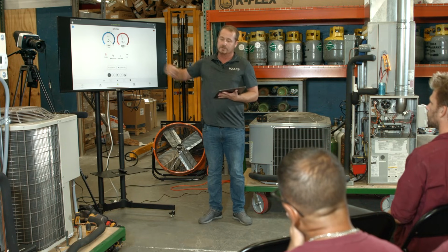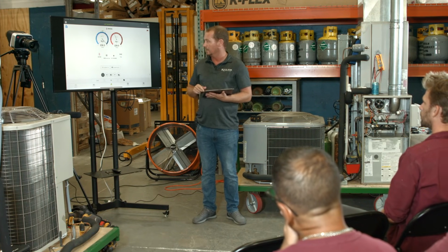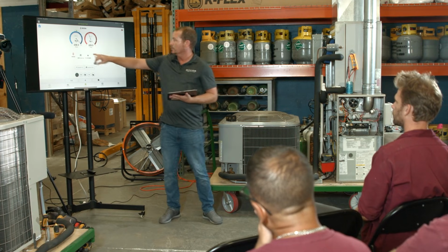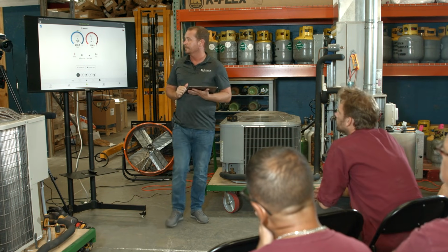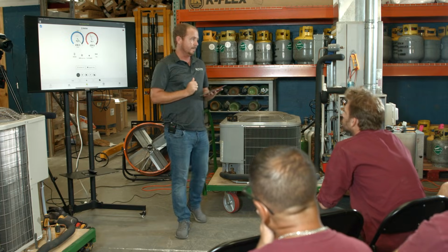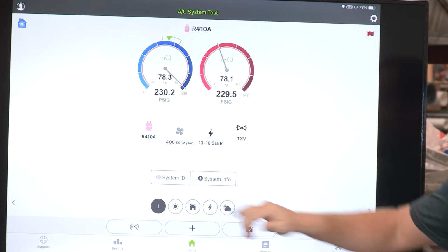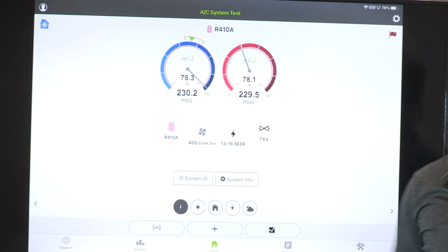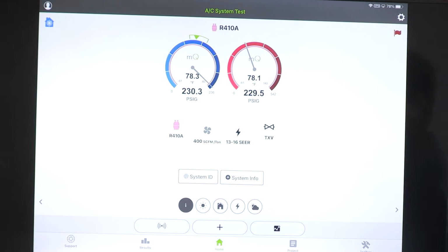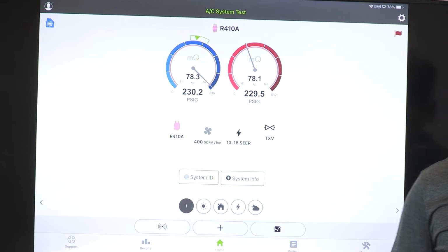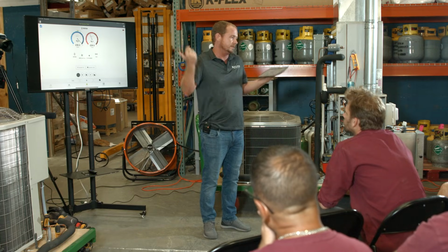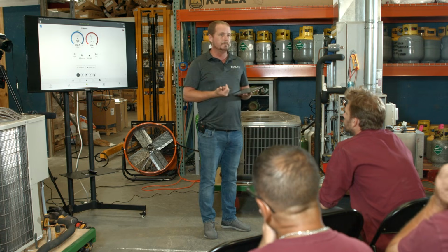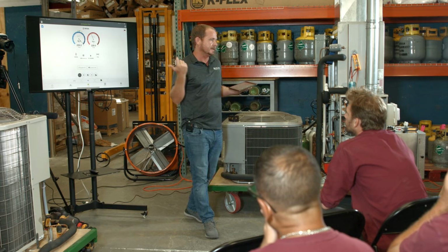If you look here at Measure Quick, which we've got, a live stream from the system, you see that we've got a slight difference between the high side and the low side, which is just going to be a calibration difference between them. But it's in the acceptable range, right? We're under 1 psi. Now, what is the acceptable range? It depends on what you're doing. But for these purposes, within 1 psi is just fine. Not going to make a significant difference.